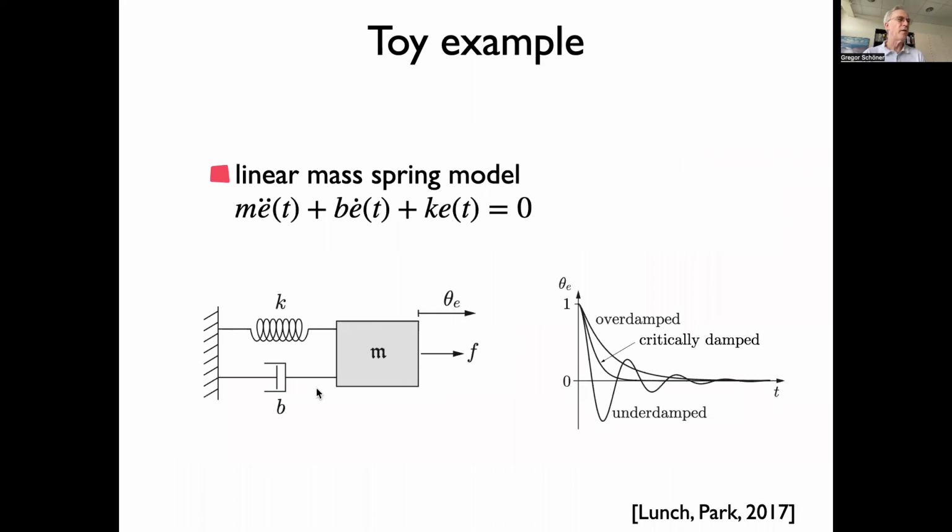So here an example: if you have a mass that can be characterized by an elastic component and a viscous component. So this will be the elastic, this will be the viscous component, this will be its general equation of motion. Then you can understand how the elastic component contributes to the oscillator system, and the viscous component would be what determines in which regime you are here.